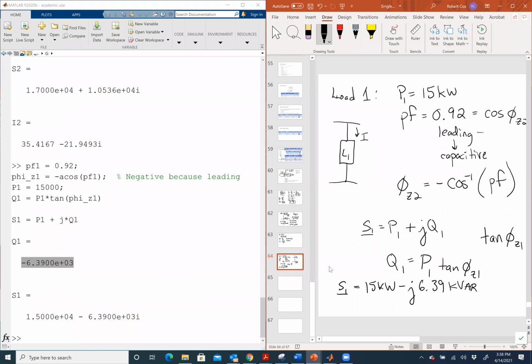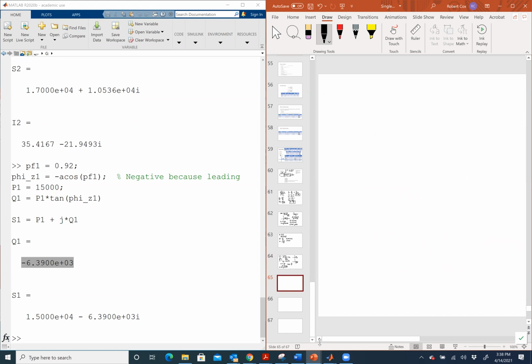Now what I want to figure out is, in this picture, the current going in there. Now we know that the voltage across it was V1, which we solved for with our transformer relationship. So if that's the case, what would the current going into that thing be? How would I figure out the current? We did a similar thing on load 2, right? Load 2, we knew the voltage. We don't know an impedance, but we do know power. So how do we do that then? S1 over V1 looks like the conjugate of I.